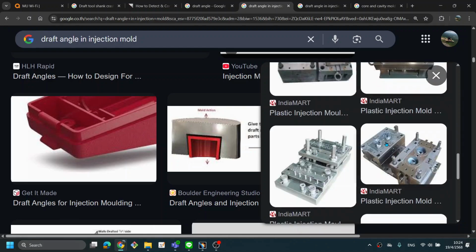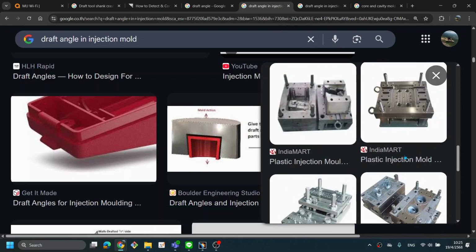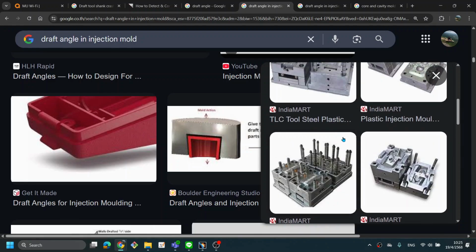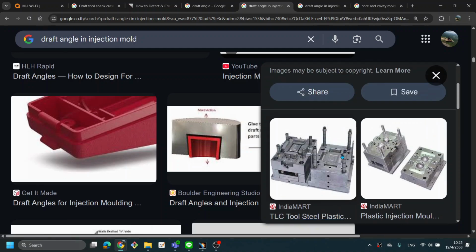That is a real one, and for us, I will teach you something different, because I will use a mini CNC. The mini CNC is limited in power, and you cannot use steel as the raw material. I just use acrylic material, which is softer than steel, because the steel grade of a real mold part is very high.